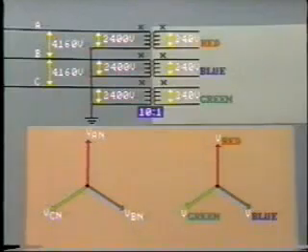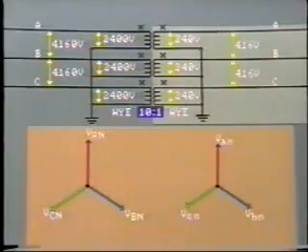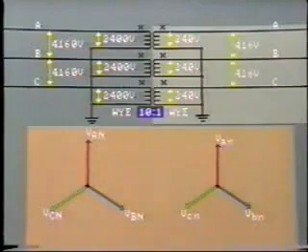Now look, we have three secondary voltages available, displaced at 120 degree phase angles. They could be connected to form a delta arrangement like this, or a Y connection like this. By following the polarity markings, we now have the correct phase relationships and line-to-line voltage, 416 volts.